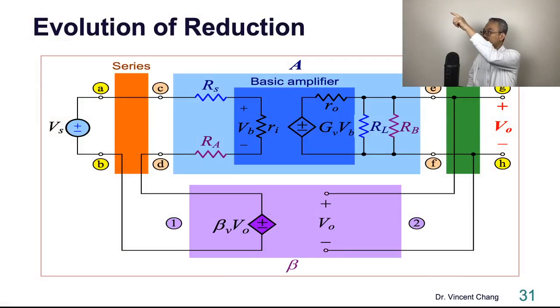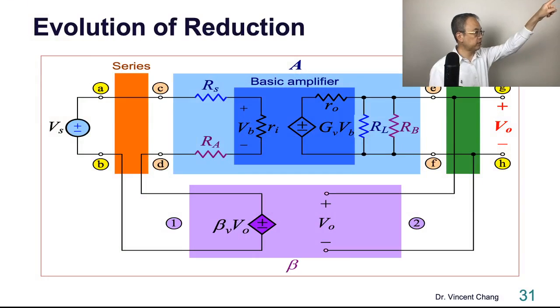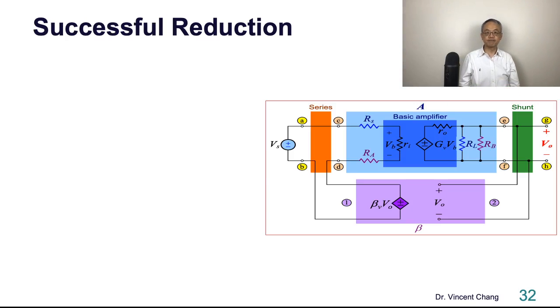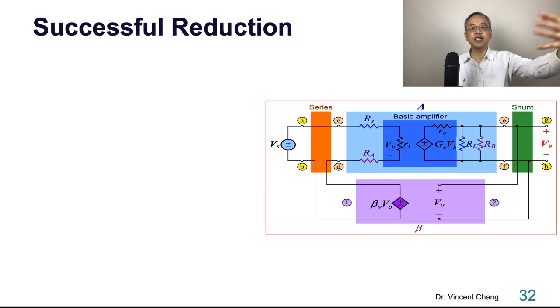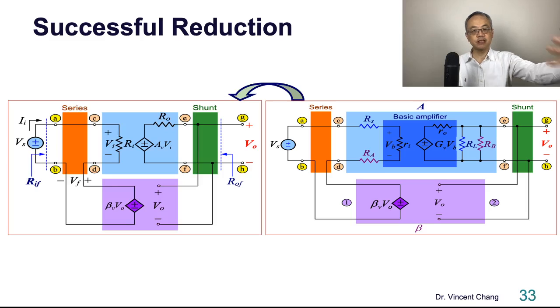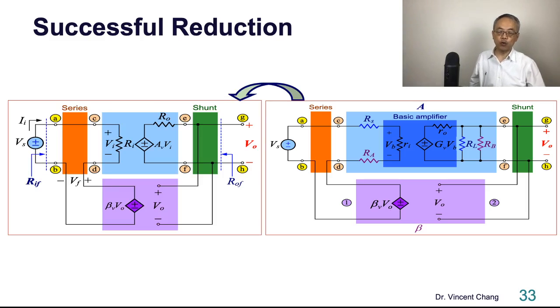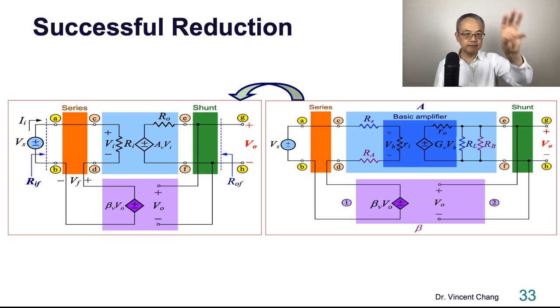You see series mixing, ideal case. Shunt sampling, ideal case. And looking down, voltage control, voltage source. So it's the path of reduction. So now let's try to clean up the black box. We can just combine the three resistances on the right into the one, the capital Ri.